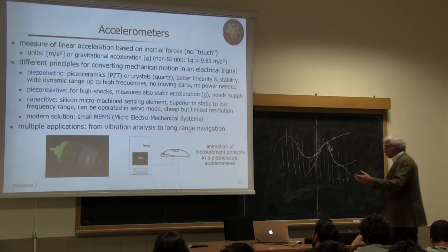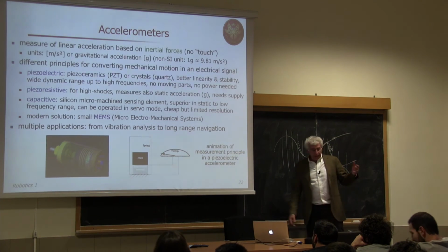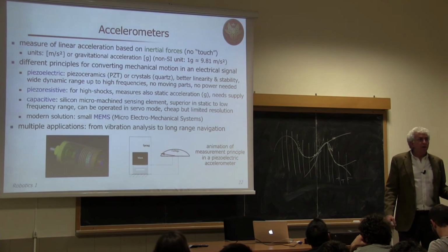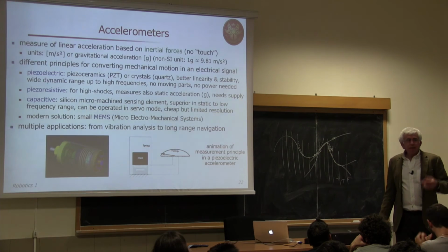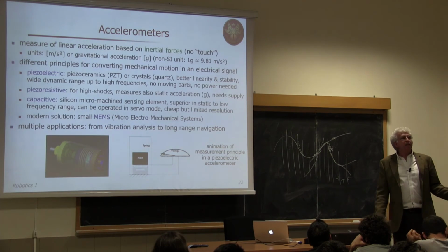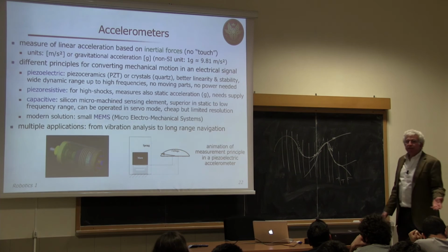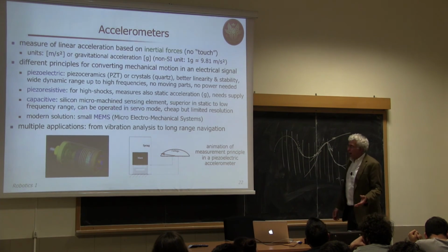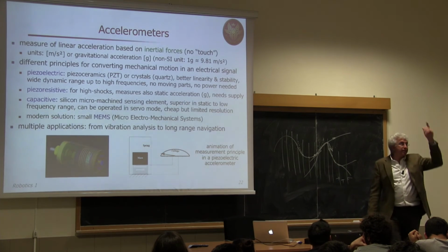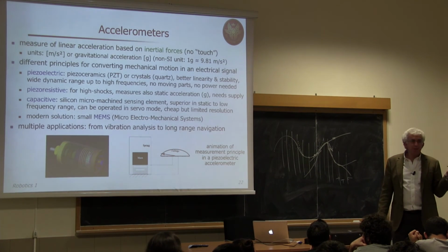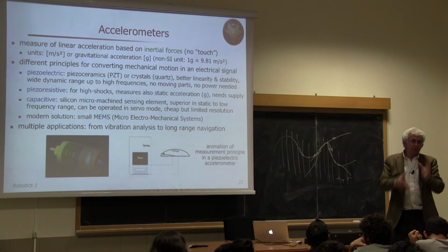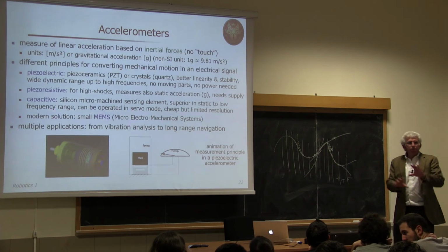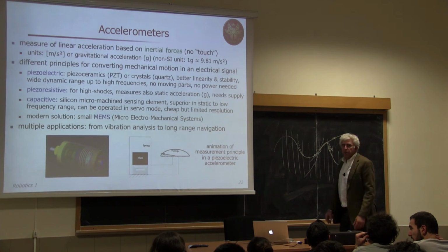Accelerometers were certainly inside the body of the Sony legged robot dogs, but they are also in your smartphones as MEMS accelerometers. Why? Because you need to sense the acceleration of gravity, for instance, to change the landscape view on the screen.